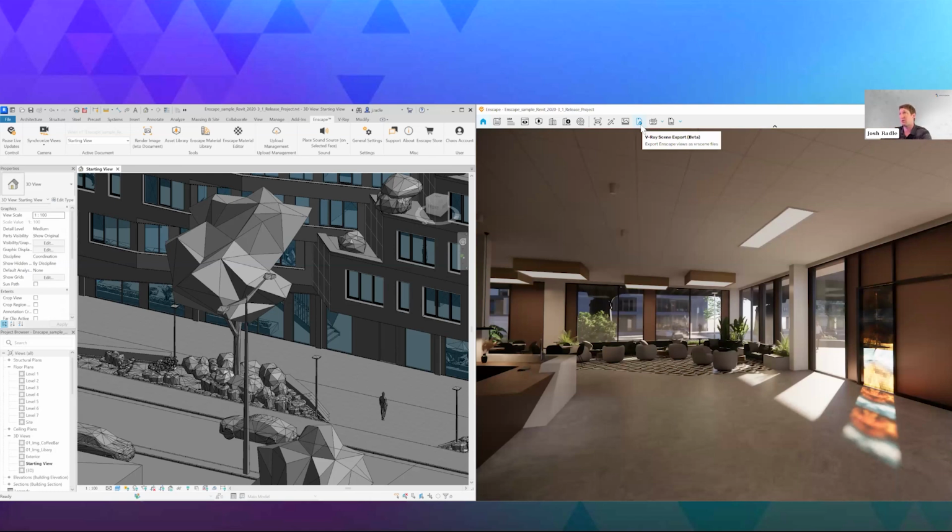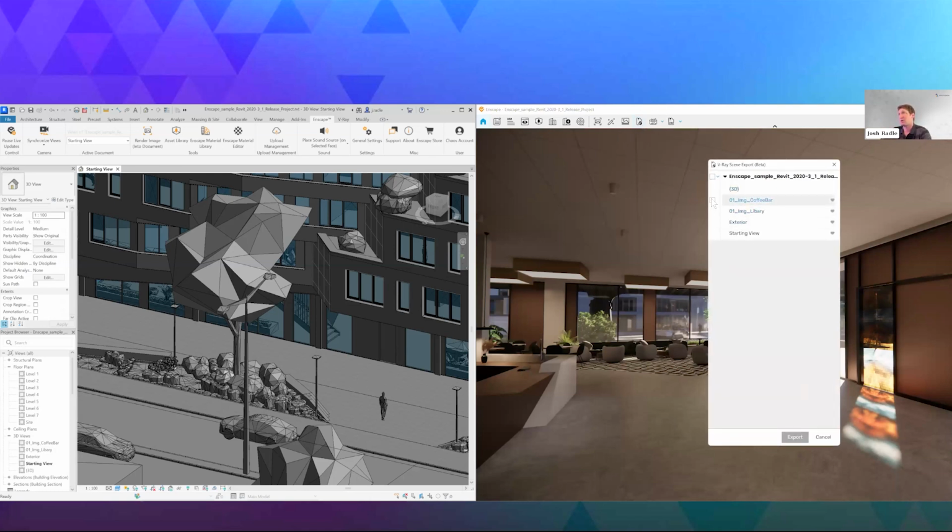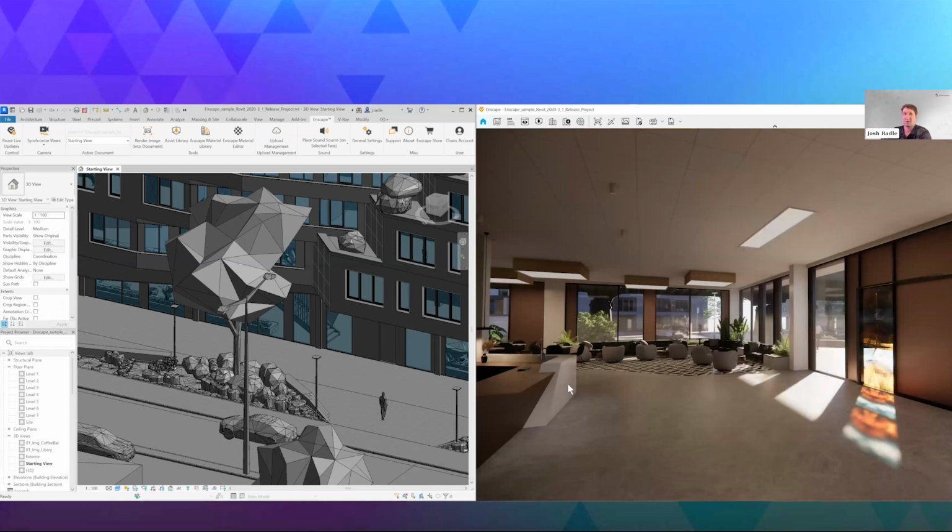With this VR scene exporter button, you can export a scene from Enscape, and it's going to take all the geometry, all the materials, all the Enscape assets, and then you can send that to your ArcViz artist. They can go into V-Ray for 3ds Max, go File, Import, and that'll bring all that geometry across. It'll bring all the materials across, automatically convert them to V-Ray materials, and they'll be able to see the Enscape assets as well. And the camera position will come across too. So it gives them a good starting point going forward, so they don't really have to start from scratch.